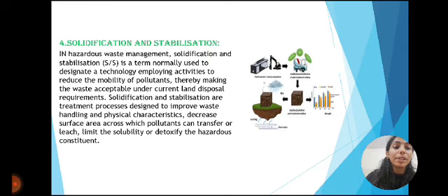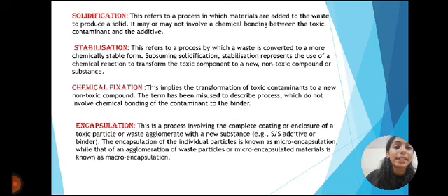Solidification and stabilization are treatment processes designed to improve the waste handling and physical characteristics, decrease the surface area across which pollutants can transport or leach, and limit the solubility or toxicity of the hazardous constituent. Solidification refers to the process in which materials are added to the waste to produce a solid.